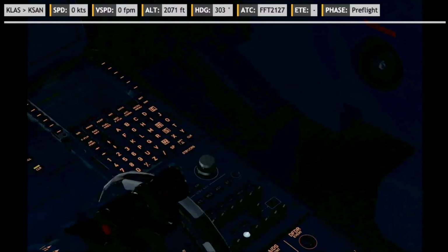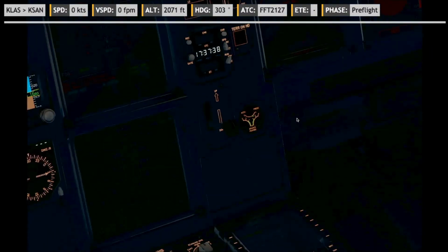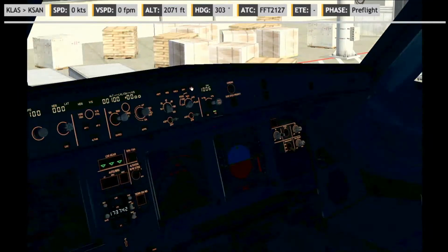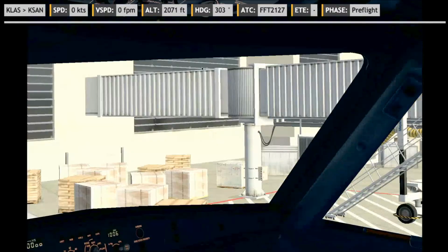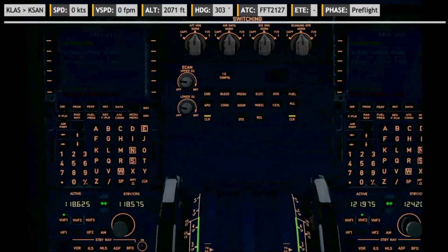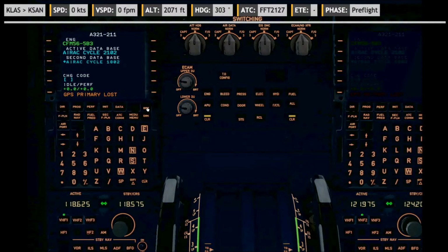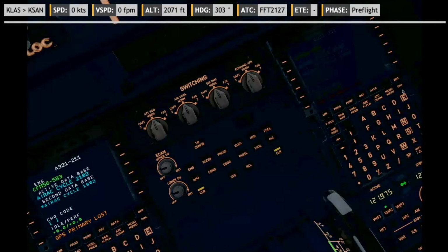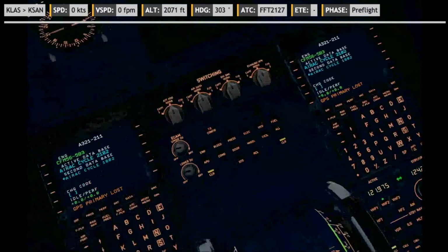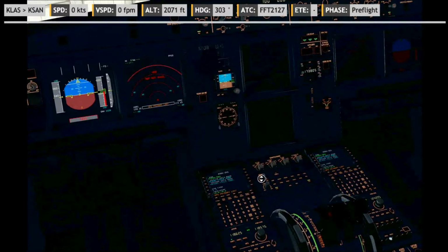Turn on the 3rd radio. Get everything set up here. Auto brake's not required yet. And that looks like we did all of this setup. Then we can start initializing our flight management and guidance system. So first we want to get these lights up and bright. Same goes for our first officer's display. Also, maybe I want to have the ECAM lights up and my first officer's PFD and navigation display.